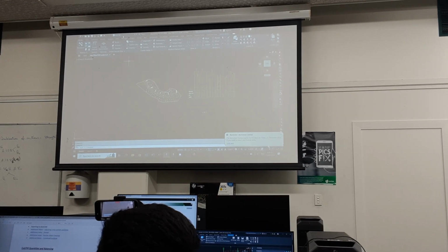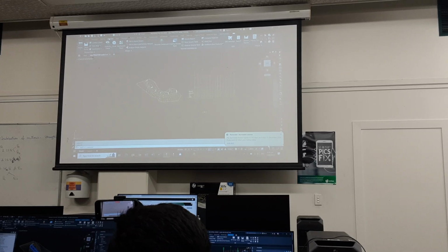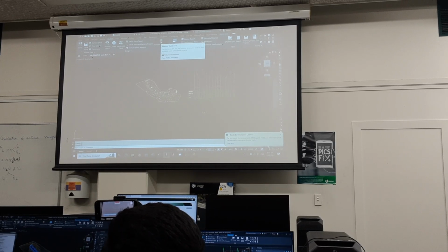Okay. So under Analyze, along the top here we've got Analyze. I'm clicking on that, and there's a volumes dashboard showing the cut and the fill.